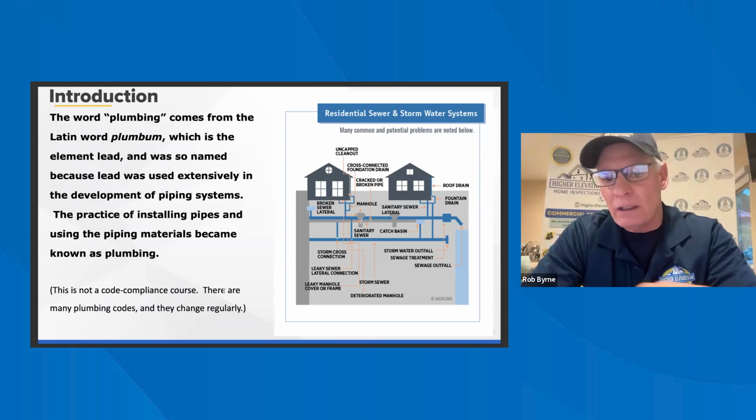Expansion tank on the boilers. The boilers and water heaters, hot water heaters should be provided with an expansion tank. There's two types of expansion tanks designed for use on residential boiler systems. Non-pressurized is a simple cylinder filled with air set at the atmospheric pressure. A pressure tank is sealed, cylindrically divided by a flexible diaphragm. That's what you're looking at here. Right above the label here is that diaphragm we're talking about.